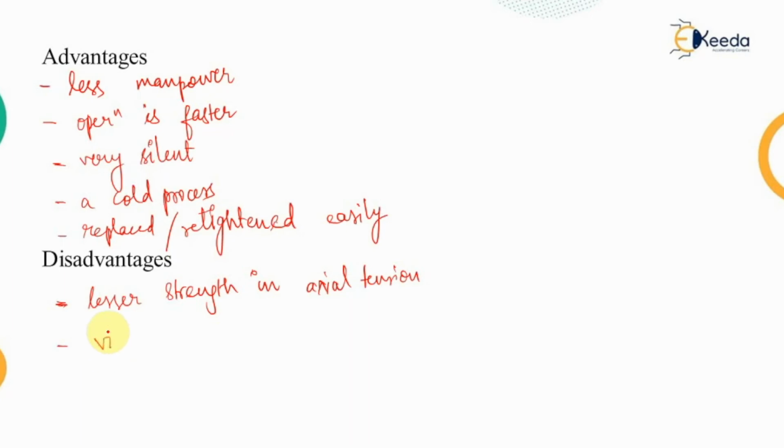While in the case of vibratory loads, for example in the case of bridges where vibrational load becomes active, the connection, since it has been provided with the help of these tightening screws, may get loosened up and therefore it has to be tightened again.